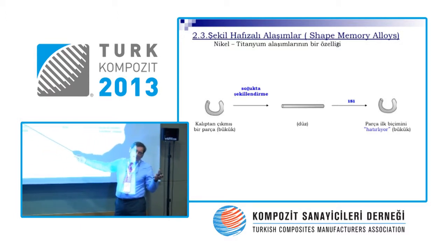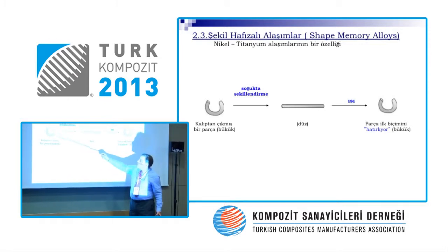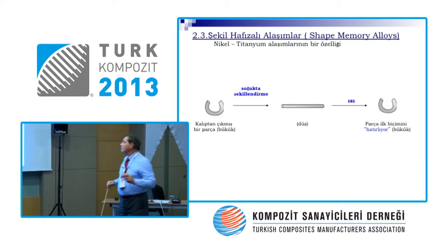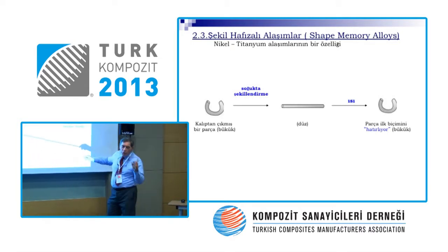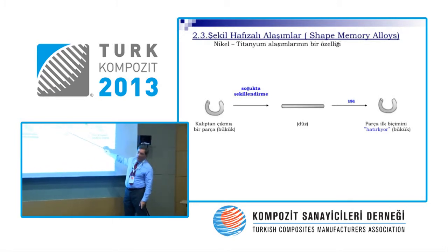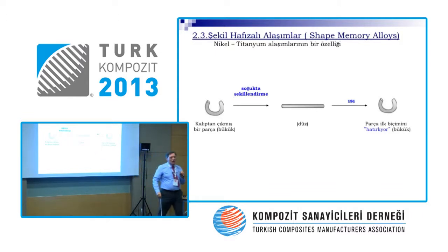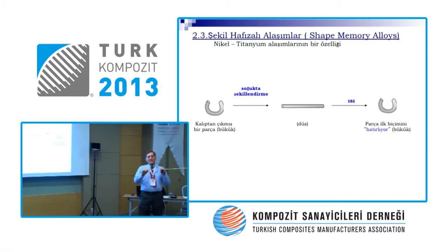So you have a metal alloy that has been molded in this geometry. We pour it, take it out of the mold, but later on, with cold forming, it was bent, but we opened this up, the form has changed, and it's now straight. So this is actually the memory of the form. If we reheat it, it will return to its former form. The crystal structure of this alloy can remember somehow the previous form.